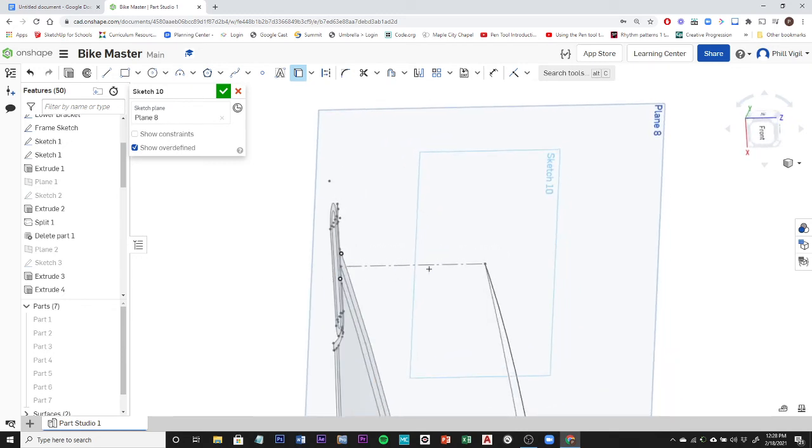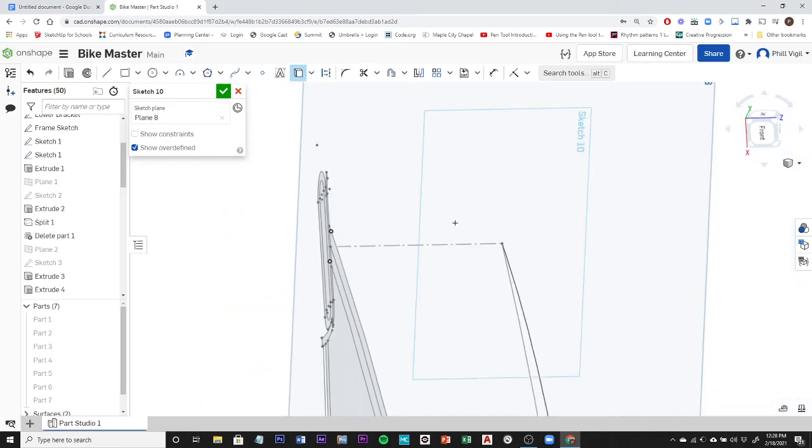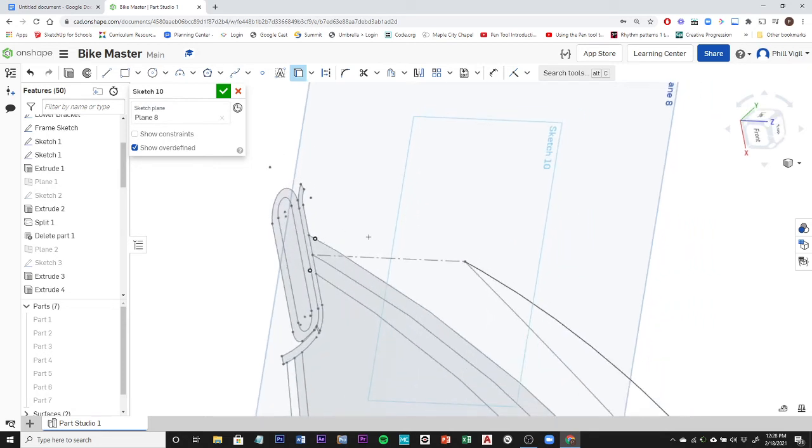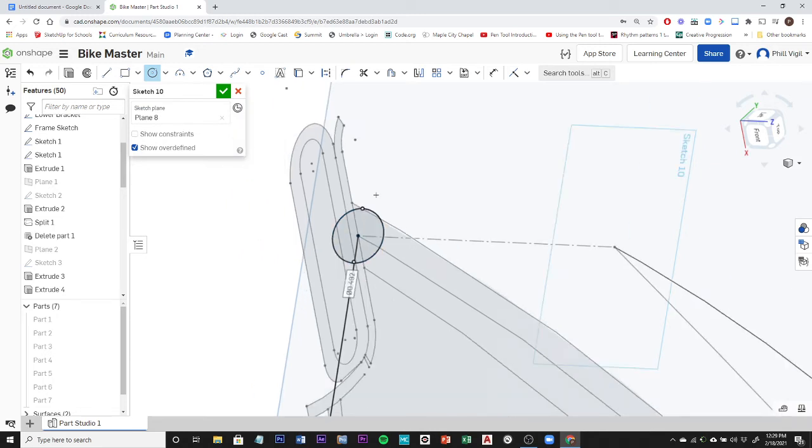Alright, so we can see that they are intersecting right here, not over here. So I'm going to need to draw my circle down here first, which is not a problem. Go ahead and grab the circle tool. Try to reference this center point, so I'm going to need to grab that as well. Go ahead and use the use tool and reference this line here. Now I can use the circle tool. Click on that point and then choose one of the outer points to create the circle.